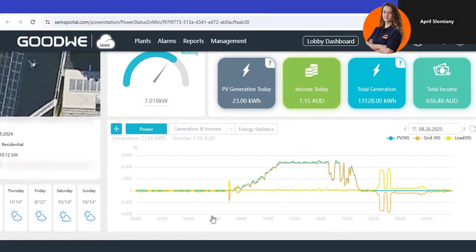If there was a battery installed at the home, not one on this site, but it would add an extra grid draw that would be called a battery state of charge. It will show you a reflection of how the system charges up in the morning and then discharges in the evening. On a site like this, you'd probably reach full charge by about mid-morning, and then you'd see the home start to draw on that battery capacity throughout the evening and afternoon. The grid draw would look something like a bell curve on a site like this, as it does on most homes.